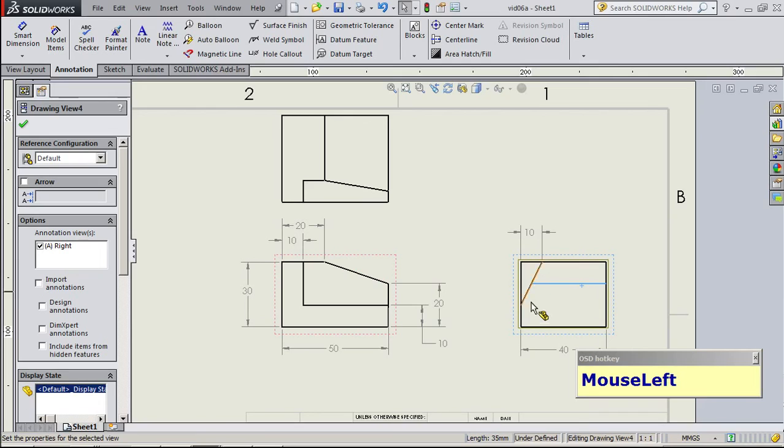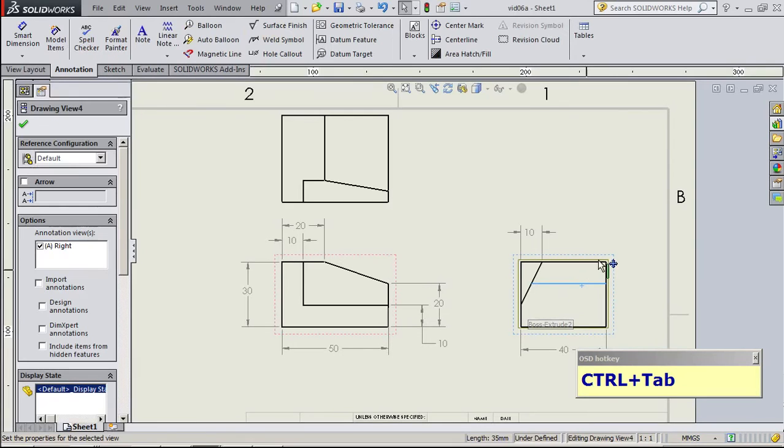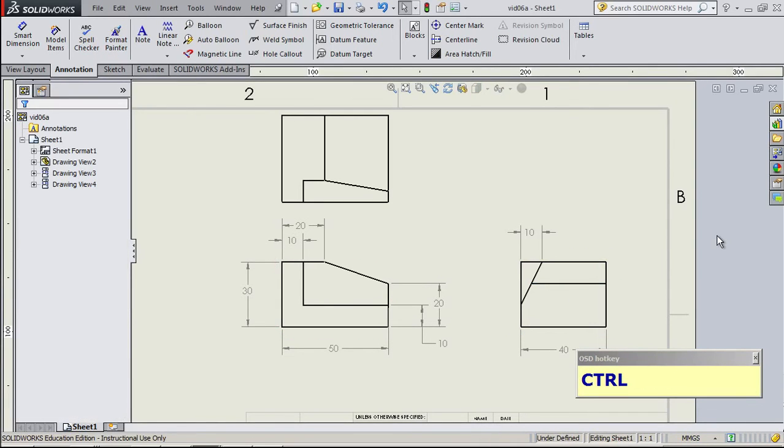And if I wanted to figure out where this edge ends, I refer to this view and find out this is at 10, so I already know that. Notice that I'm not giving this height because it gets interpreted based on where the intersection lies. This height is interpreted where this line and this line meet, so I don't give that value either. Save.